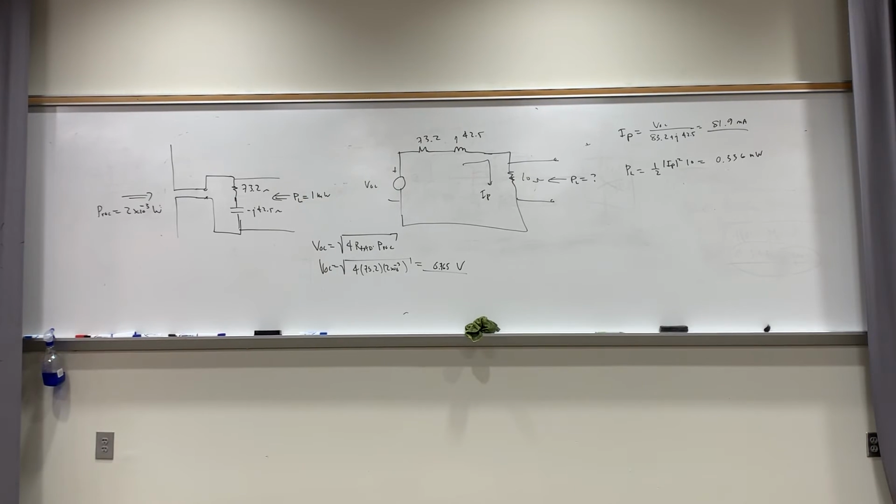We did the horizontal wire problem, but if it was a vertical wire, it would be doable as well. That just means it looks like twice its length, right? Only that the fields don't radiate into the ground plane. So it's the same electric fields as an antenna twice the length of the monopole would radiate in the upper half. The radiation resistance is halved and the directivity is doubled.